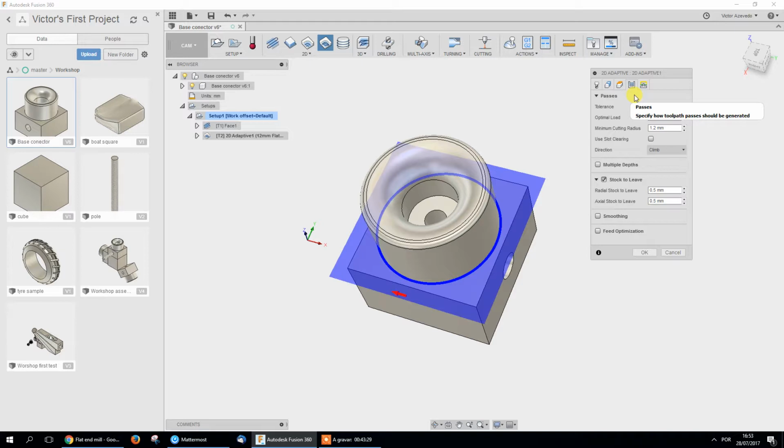I'm saying this because most of the time when people start machining, they activate multiple depths and use only the tip of the tool to remove 1 millimeter of the whole area. Let's say this is 12 millimeters; they will use 1 millimeter of the whole 12 of the tool to remove material. That's the wrong way of doing things. If the tool has 40 of cutting height, we're trying to use the whole 40, not wear only the tip.